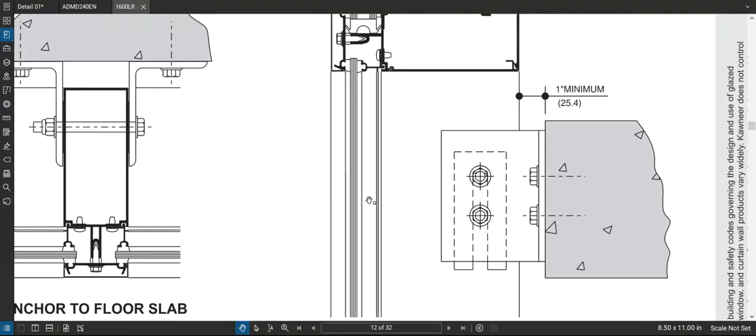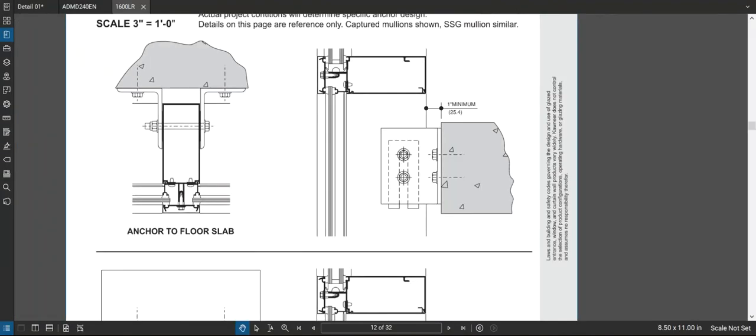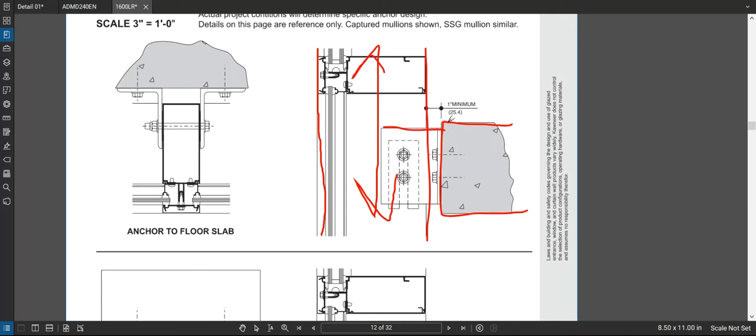And so just looking at some manufacturers literature here just to see the difference. This is a curtain wall system we're looking at here. So here's the edge of the concrete floor structure in this case, with a connection to basically this is the back of the vertical mullions. So from there to here is the vertical mullions hanging outside the structure, and that's just the connection to hang it off the structure. So that connection would happen pretty much at every floor level. Sometimes there's girts in between floors if you're going multiple floors or what have you.